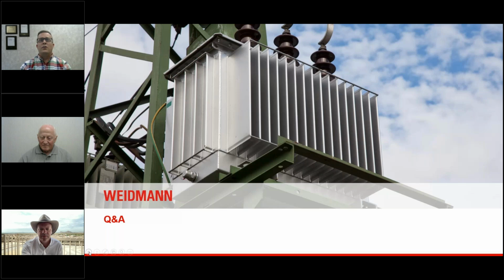Yeah, no. So as layer insulation paper, it's typically offered with the epoxy diamond pattern adhesive because that layer insulation material, you want those epoxy dots there for the short circuit strength of the coil. However, we do realize that in some of these kinds of transformers, the high voltage wire in particular can be insulated with paper instead of with enamel, for example. And so you can use thinner DPE for those applications, even with the dots typically. As far as being offered without the dots, that's something that we could discuss, as a future potential.